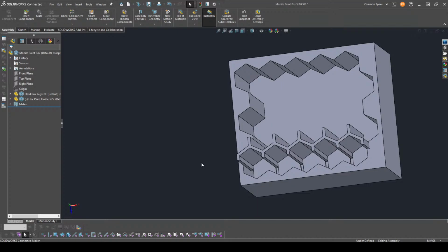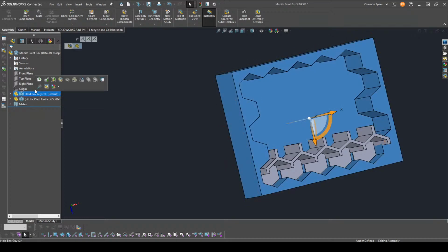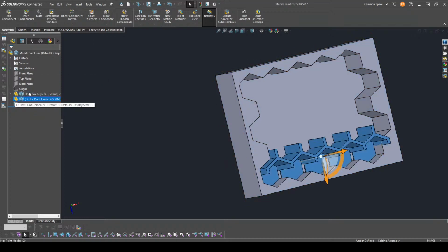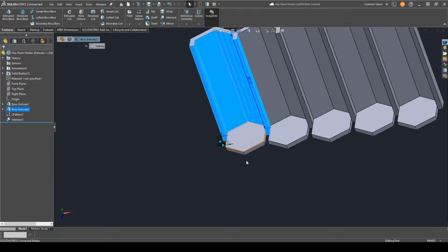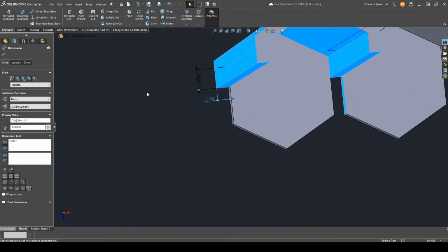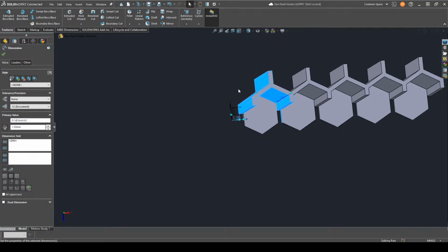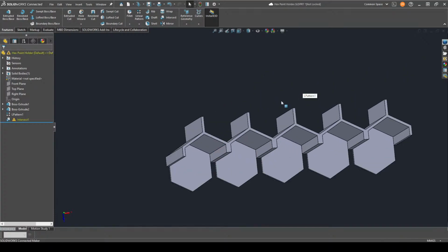When I'm talking about using your datums to help define where things are, this is kind of what I'm talking about. Using datums to define these features would mean that you don't run into situations like here. Let's just say I go into this guy and open it up. I don't like the look of this wall here. Let's just make that 1.5. I'm just feeling like 1.5 is a better dimension for that guy. So again, I didn't edit it in the sketch, so I'm gonna have to regenerate this thing, hit the little stop light, and then it gets skinnier.